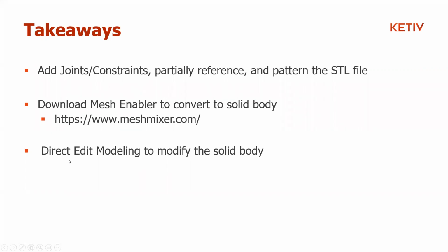Things like the tapered holes might be a little bit easier to modify, but if you're diving into some of those fillets that you saw there, that can be a little bit more complicated. And if it's just a simple part like the one I went over today, maybe it's something that you'd just consider doing from scratch even. So there's always an option. It's just a matter of what's the fastest way to the end result that you're trying to get.